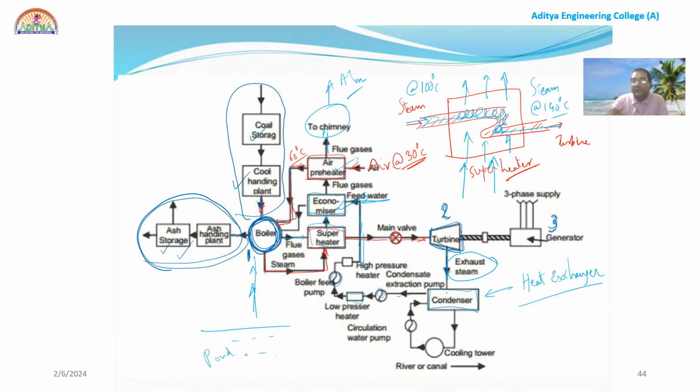In the heat exchanger, the heat will be extracted from the steam and I will get water, right? So from the cooling towers, the temperature is decreased and I am getting water. These condensate means simply condensed water, right? Steam condensed to water. This water again will be pumped through some boiler feed pump. Again, it is going through the economizer, right? Now, everything is over.